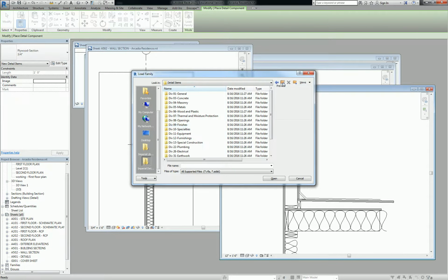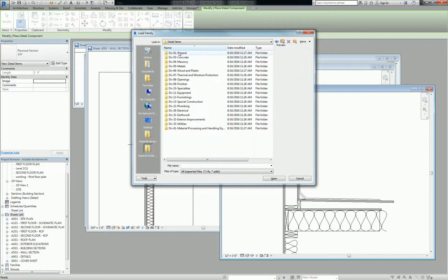Oh, by the way, I should mention what this is real quick since we're here. In the world of architecture, we have what's called specifications, and it's kind of the counterpart to our drawings. Basically, that makes up, for the most part, our whole contract documents, which means, let's say you're the contractors and I'm like, okay, here's the project, I need you to build it. You can't do everything off of just the drawings. You have this giant book that's called specifications.